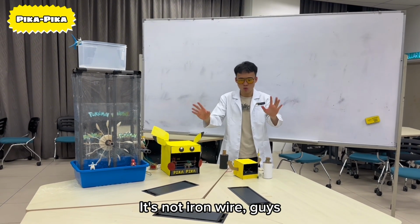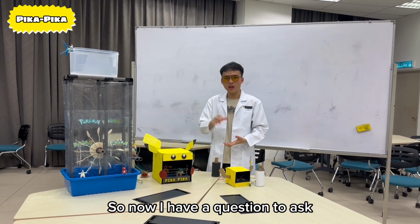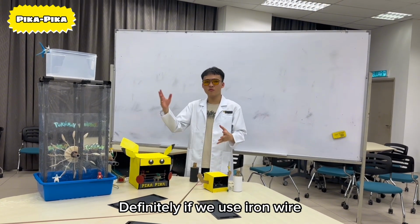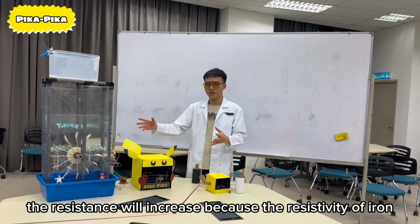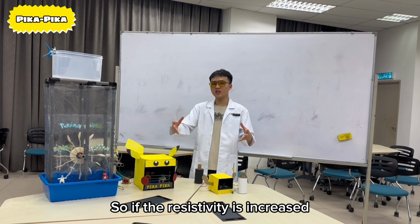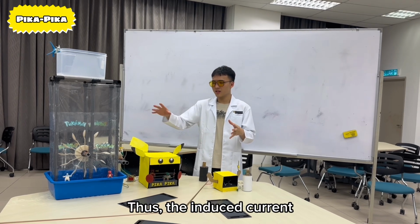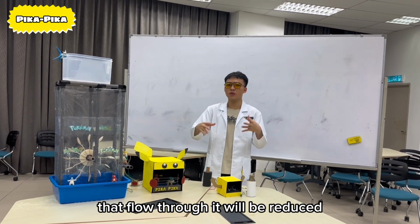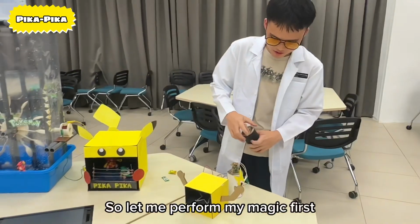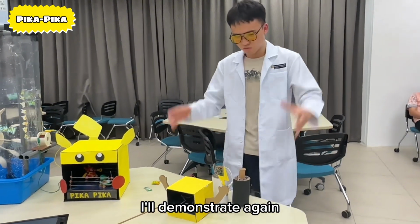Wait. It's not iron wire, guys. It's copper wire. So now I have a question to ask. What if iron wire is used? Definitely, if we use iron wire, the resistance will increase because the resistivity of iron itself is much higher compared to copper. So if the resistivity is increased, the resistance of the whole wire will increase. Thus, the induced current that flows through it will be reduced and the light bulb will be dimmer. Alright, so let me perform my magic first, and once everything is fixed, I'll demonstrate again.